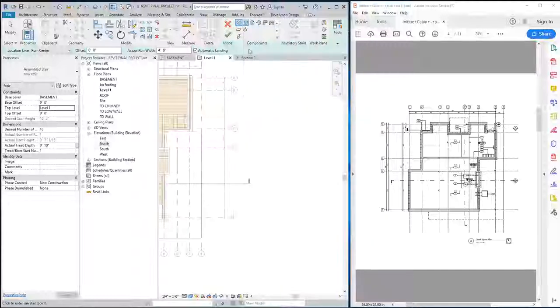So components meaning you see this little stair right here? That's a run. So if I click on run and I use one of these different predefined stair types, we have straight, we have spiral, we have center end spiral, we have a winder, and we have a U-shaped winder. If I pick one of these shapes in combination with this little guy, when I draw my stairs, they're automatically generated.